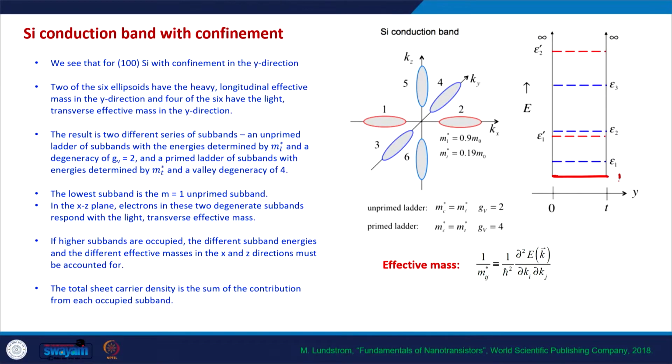Okay. So almost all the MOSFET theory will be the same. Here, instead of EC, which is the bottom of the conduction band, we need to consider EC plus epsilon 1 if we are considering just the first subband. Okay. So all those calculations will be modified in this way. The number of channels in the MOSFET, the density of states, all these things will be modified in this way.